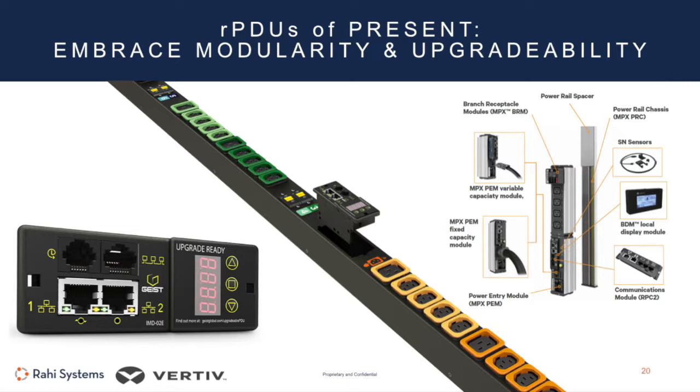So if the next tech refresh the user undertakes requires C19s instead of C13s, there's no need to rip and replace the entire PDU. A different module can be hot swapped, everything being touch safe, and you can have the right combination of outlets in the right rack location. So two different takes on the concept of modularity within rPDUs.